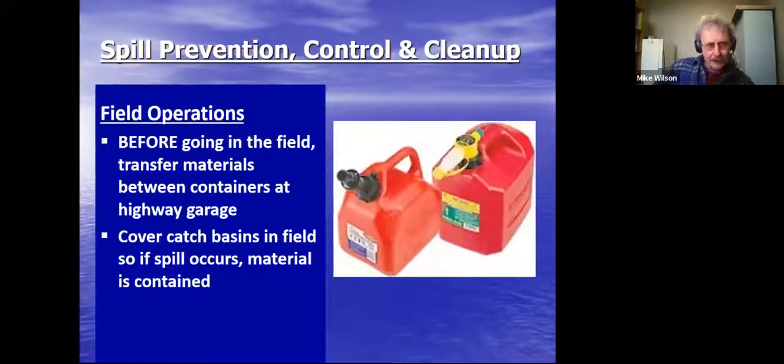In terms of spill prevention for daily field operations, before you go out to the field, transfer materials if need be. If you only need a gallon of gasoline, there's no reason to take 5 gallons. If you have a 1-gallon can, transfer that material in the shop where you have Speedy Dry and all that material available if for some reason there is a spill. If you think a spill may occur and you're out in the field, cover your catch basins. This way your material is contained. They make special covers for catch basins now.